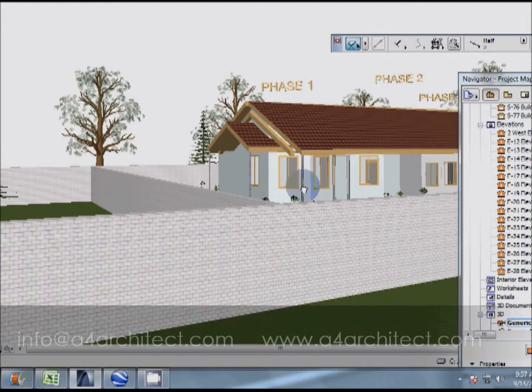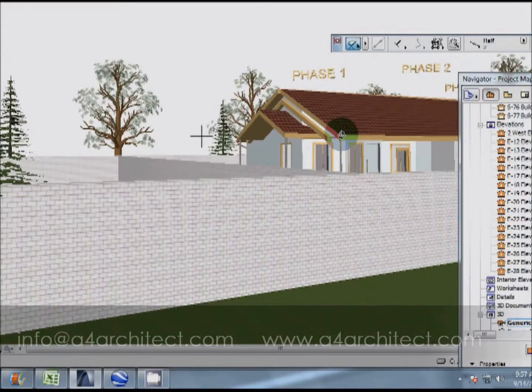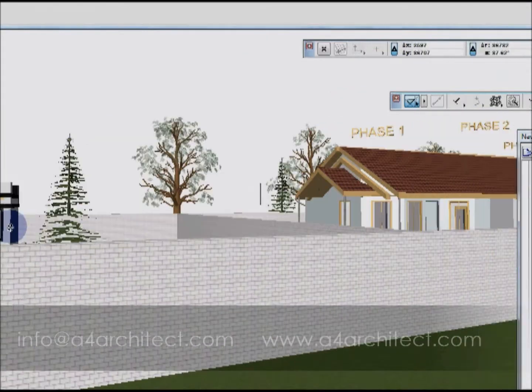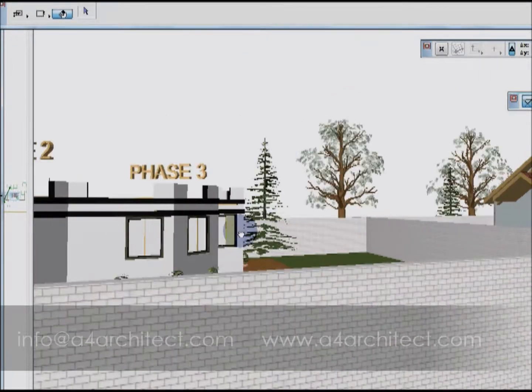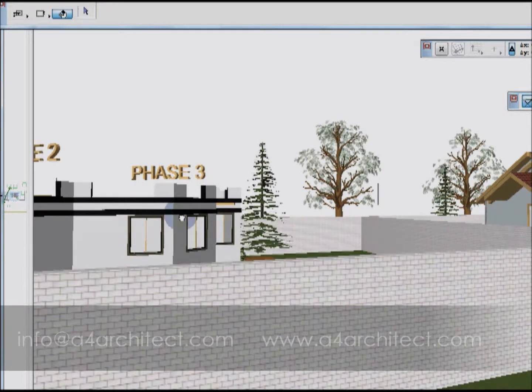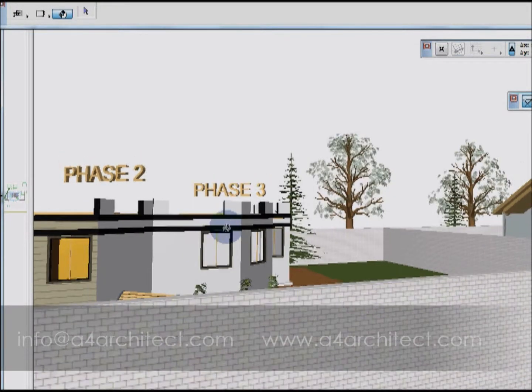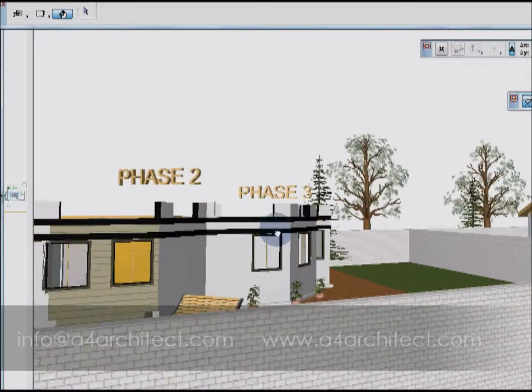And the savings is in that this surface area, if you can see, is far much larger than when the roof surface is slightly close to flat. This roof surface here is around 6 degrees in steepness. So there is a major savings in terms of roof material. Then again, the timber structure, the roof frame that supports.